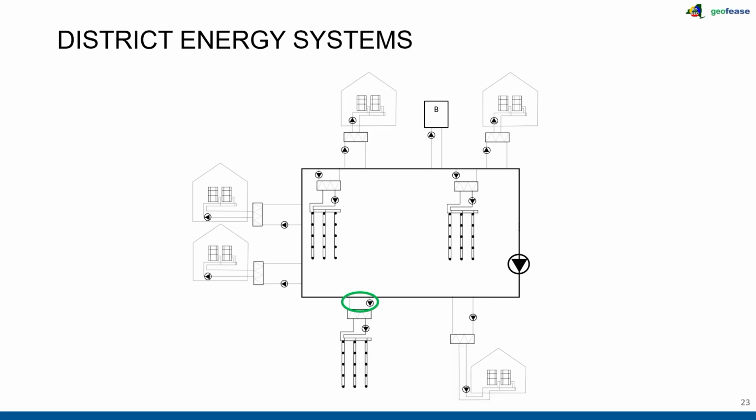They want to understand the customer side: how many BTUs is that customer pulling? They also want to understand the ambient loop pumps, the kilowatt hour consumption of those pumps, and the backup equipment, whether that's a dry fluid cooler, a boiler, or any sort of, again, thermal balancing equipment, as they call that.